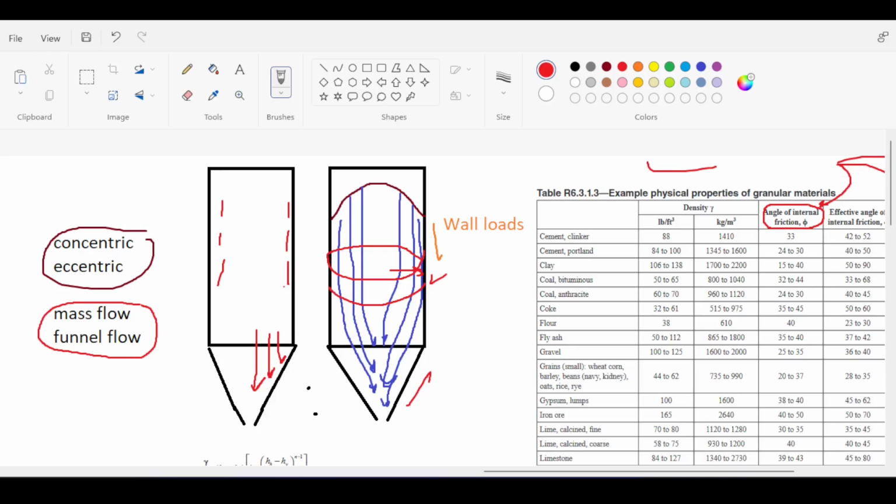You will even see that the equation has to do with the area of the silo versus the perimeter of the silo, because the area of the silo is part of the load causing the pressure, because gamma multiplied by A multiplied by H would be a full force. But still, the perimeter also plays a role because the perimeter is related to the friction, which tries to alleviate the pressure on the hopper. Well, this is in static conditions, but imagine the dynamic conditions now.